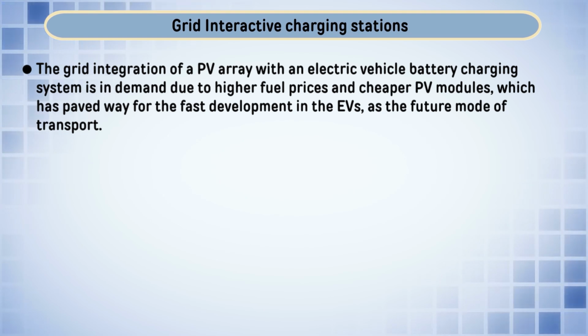So, what are the disadvantages of a conventional charging station? For protection reasons, conventional charging stations are mandated to shut down automatically at loss of grid. However, the presented charging station is developed to establish continuous power supply to the vehicle as well as to the consumer load. We have operated this PV based charging station in various modes like vehicle to home whenever it is operating in standalone, vehicle to grid mode, and grid to vehicle mode.